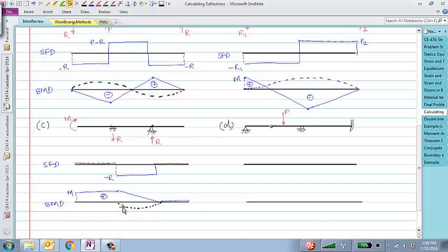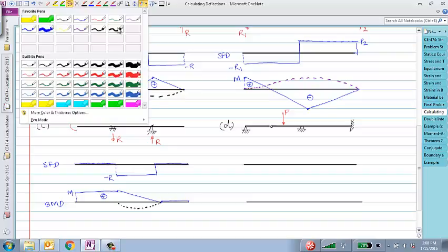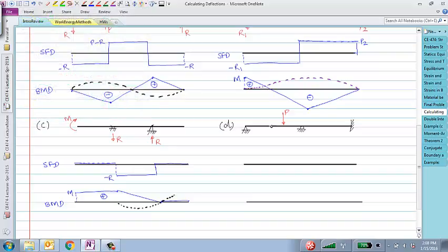Is the curvature in this middle section changing? Curvature changing in that middle section? Yes, because the moment is decreasing from some value down to 0. So the curvature is maximum here and it is decreasing down to 0 here. How about the curvature in this half? There's no curvature, it's straight. So indeed, I would need to draw that as a straight extension all the way there.